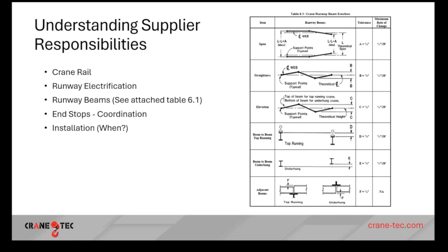But the beams do not have slotted holes on the stubs or the tiebacks that go to it. And yet we're expected to get that crane rail to within 3/8 when we have 4 times that play in the outer columns in the rigid direction. Because it's the rigid direction of the pre-engineered building frame, there's not a lot of adjustment that you can do easily on an 80-90 foot tall building, besides a crap ton of shimming and things like that to get the straightness and then the span, right?